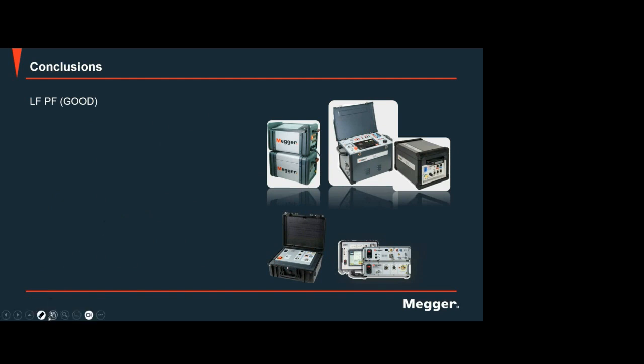Yes, of course. Remember, we don't need to have a previous test result. If you are going to do CT testing, for example, I'm just drawing a donut type, but of course it's better if you test a bar type CT. So here I have, for example, the phase A CT, phase B CT, and phase C CT. I will use the narrowband to get the frequency response of these three, and then compare them. For example, this is the response of A, this is the response of B, this is the response of C. So it's very clear that phase A has a problem.